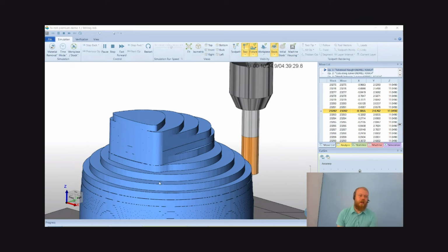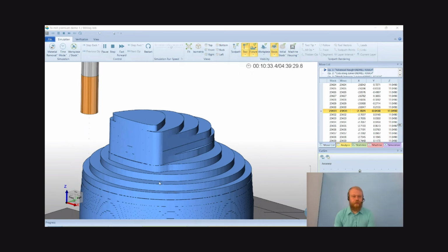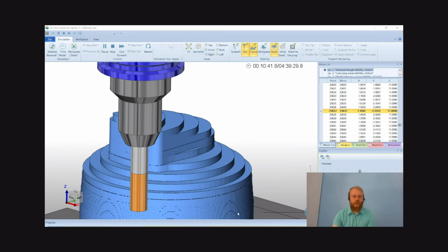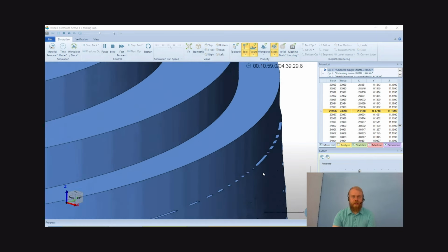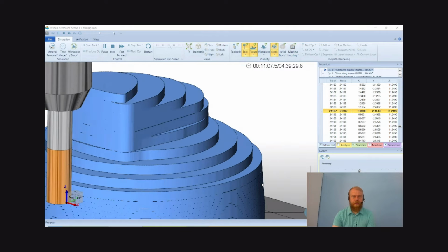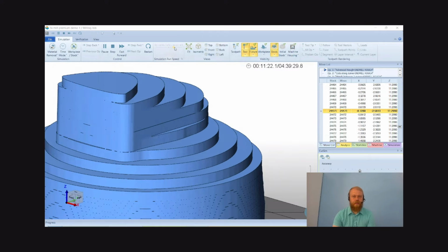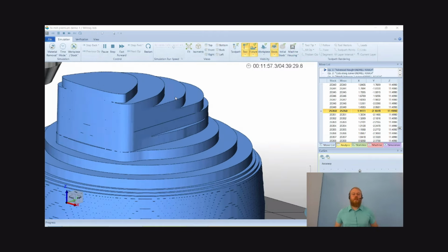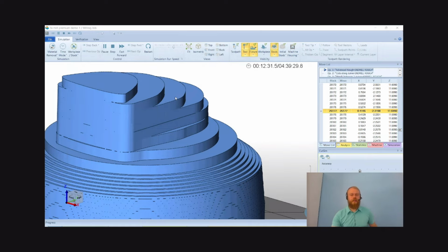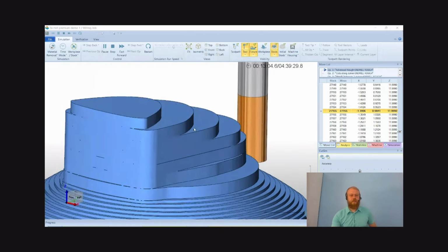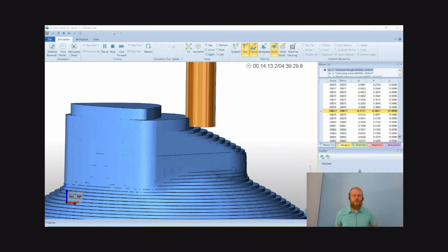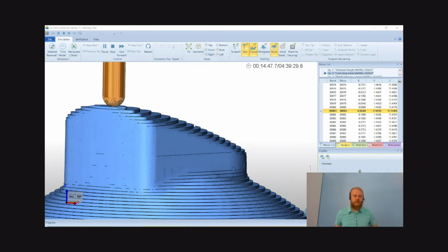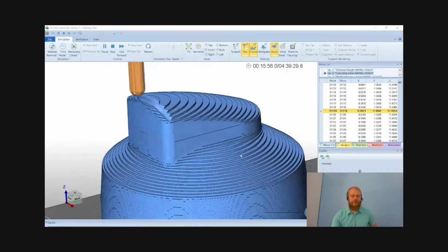So what we can do with this roughing operation, instead of doing a second advanced rough, we can do this intermediate steps option and do 3 additional steps, having the tool work its way back up, doing this stair-stepping routine to save us time with the roughing operation there. And that's a lot less material for that finish tool to cover there.